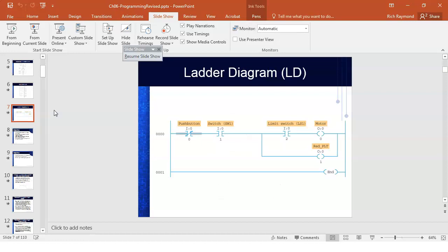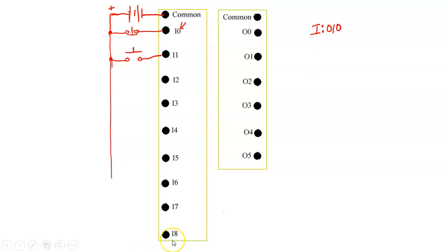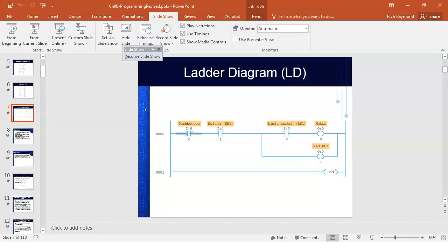They're calling them push button, and they're calling it switch 1 and limit switch. So notice the limit switch has a different symbol. So this is hooked up to port 2. So we'd come over here on our diagram and we would have to draw the legal symbol for a limit switch. So I'd come over here and it's on 2. It's normally, what was it? It's normally open.